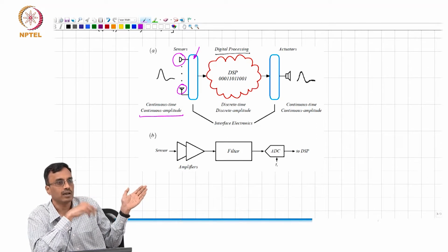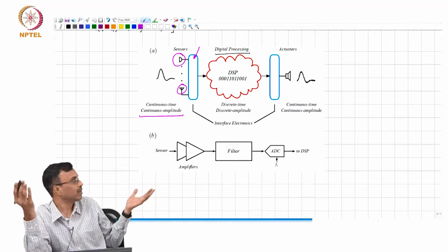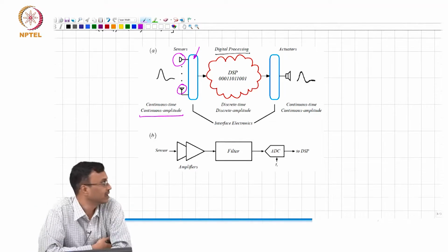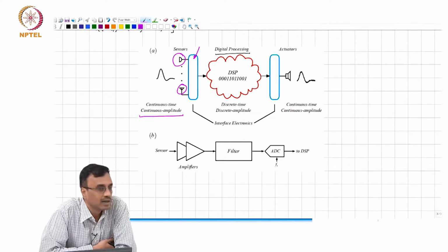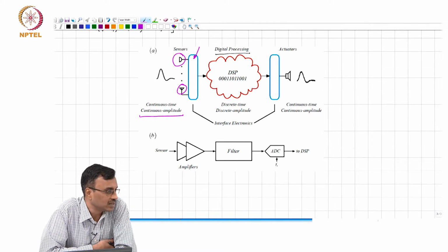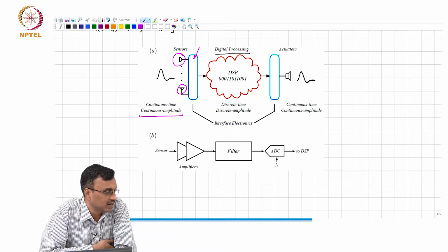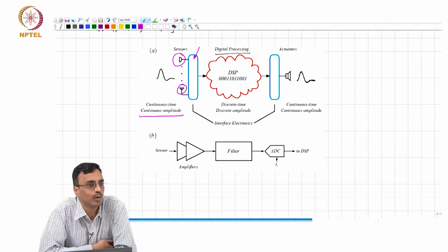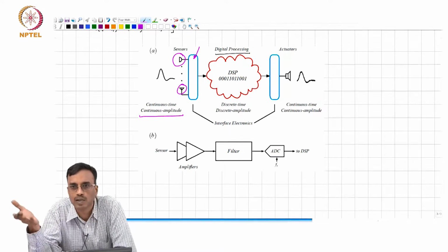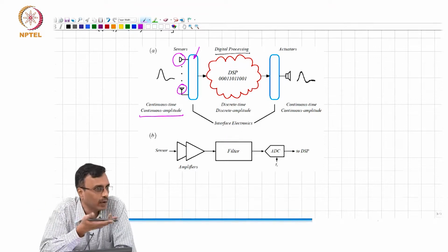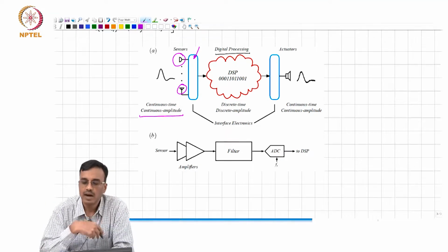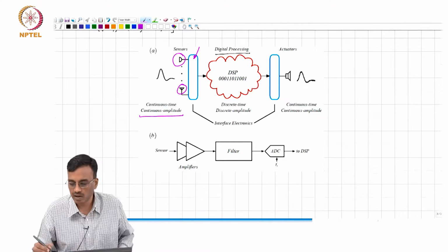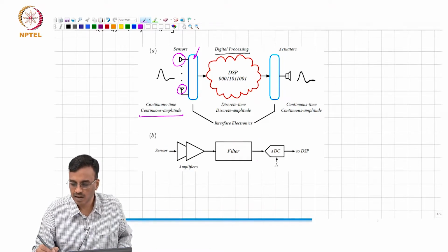How can you take a signal that is continuous in time and represent it losslessly as a sequence? Yeah, sampling. The Shannon theorem basically is telling you that if the signal is varying sufficiently slowly, you don't need to keep looking at the signal all the time. You only look at it once in a while and then you're good enough, right? And to prevent aliasing, you need an anti-alias filter.